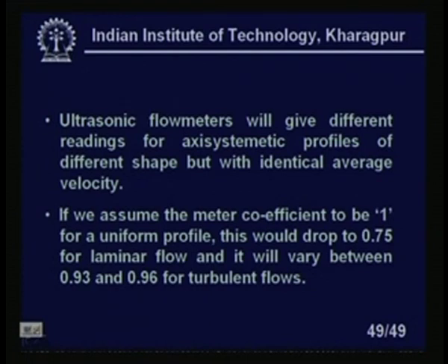So, these are the two typical disadvantages of the ultrasonic flow meter, which are not there in the case of the electromagnetic flow meter, but for non-conducting fluids we have to use the ultrasonic flow meter because of its non-invasive type of measurement technique, right. So, with this I think today I come to the end of lesson 15 of industrial instrumentation.